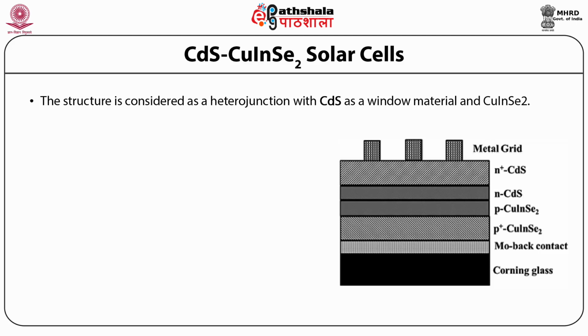Photoluminescence spectra of copper indium selenide shows the levels at the sites occupied by copper atoms, which lead to a p-type conductor in the copper-rich phase, while the n-type conduction in the indium-rich phase is observed. This complex nature may lead to buried homojunction at the interface between cadmium sulphide and copper indium selenide.